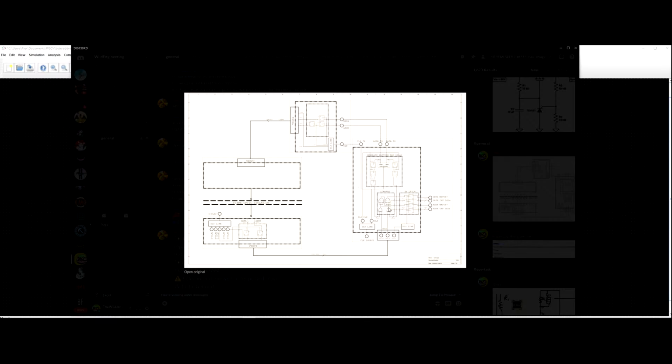And here's how it interacts with the customer boards. My board is here, and then these are the customer boards. You can see the fiber optic isolation there. And I have to manage all the clock delays because there's like 500 nanoseconds of delay all the way through the system back, and we're running at 10 megahertz, so you need to worry about those delays at that speed.